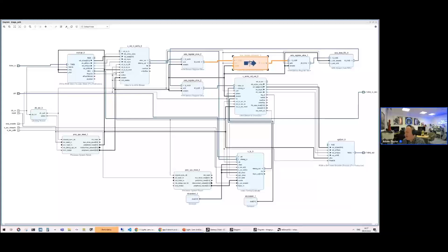Vivek, VDMA, yeah, where we use the VDMA to transfer to and from the DDR memory, typically on the processor, or maybe it's just buffered. If you go to my Hackster, you'll see an example with the AC701 where I think we use the DDR that's on there as a frame buffer.